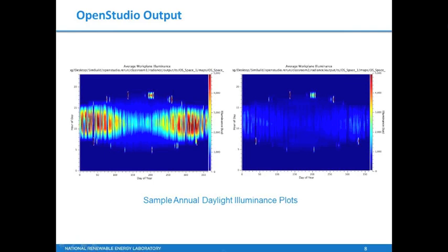And that's another thing that the three-phase daylight coefficient approach allows us to do, is to do these kinds of simulations where we can change the configuration of the windows at every single hour. In this example, it's showing the impact of a user operating a blind or a shade, but we could just as easily use this to represent electrochromic glazing, changing its tint state, or thermochromic glass, or other types of blind scenarios.